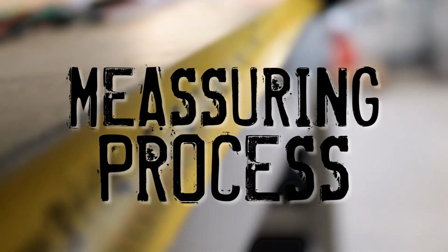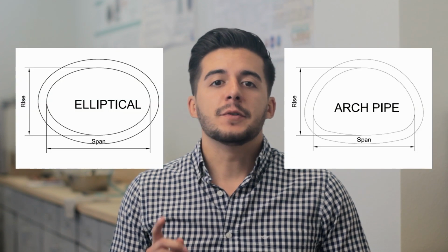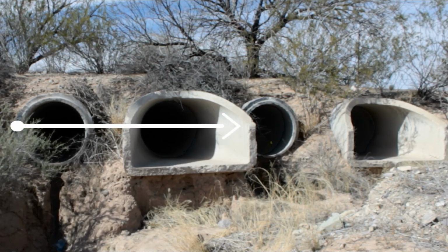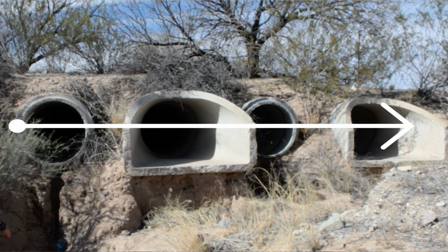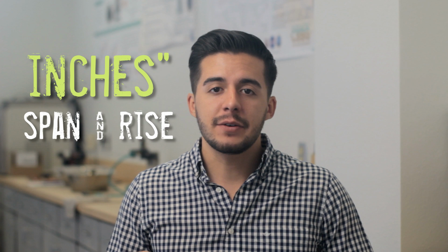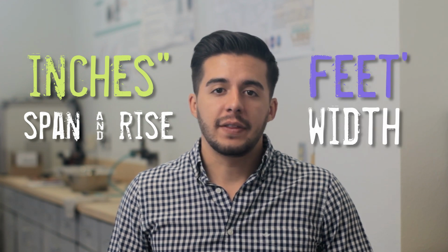Cool, we already know the shapes that the culverts can have. Now, let's learn the measuring process. The diameter of a circular culvert comes in 6 inch increments. For elliptical and arch pipes, the measurement depends on the manufacturer, but measure to the closest inch for span and rise. For multi-barrel culverts, measure the width from end to end to the closest 0.1 foot. Remember, use inches for span and rise and feet for the width.